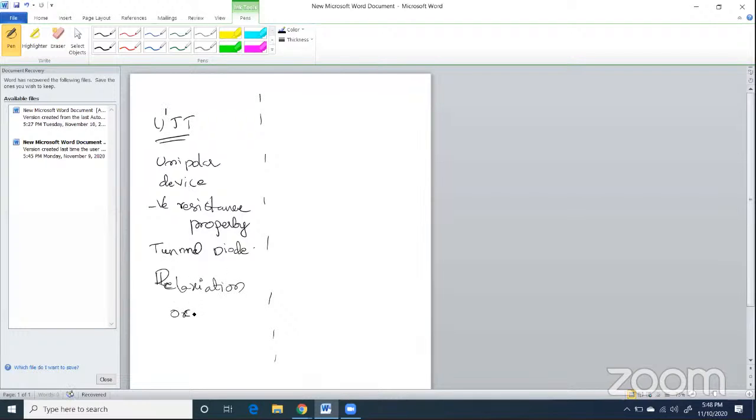All these topics I already discussed in the last class. I gave the difference between oscillator and relaxation oscillator. In an oscillator, there is no AC input, but with the use of positive feedback, the circuit generates AC output. But in a relaxation oscillator, without feedback and without AC input, the circuit generates AC output. That is the main difference. The output of relaxation oscillator is